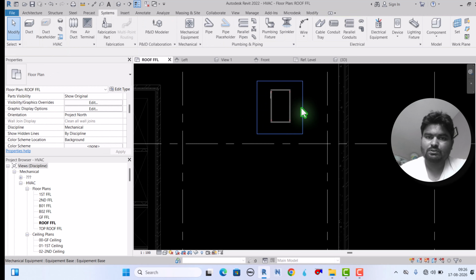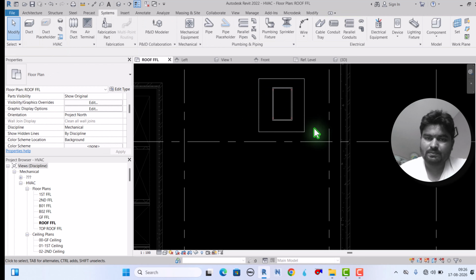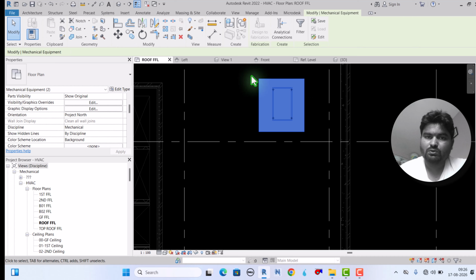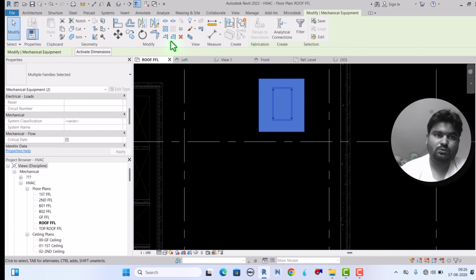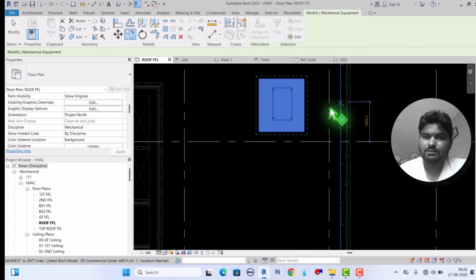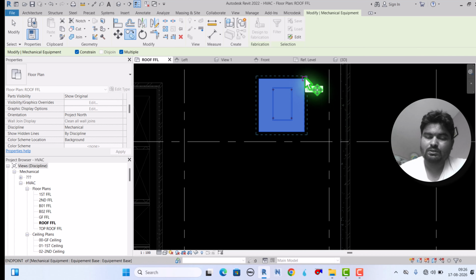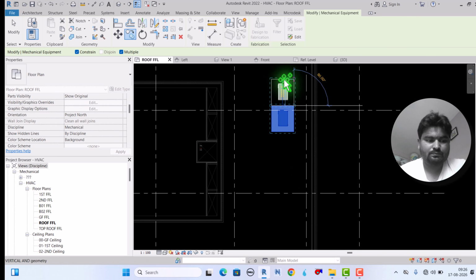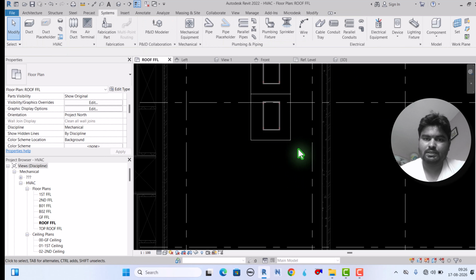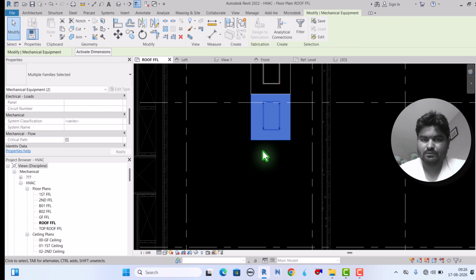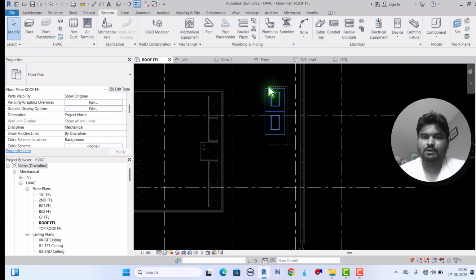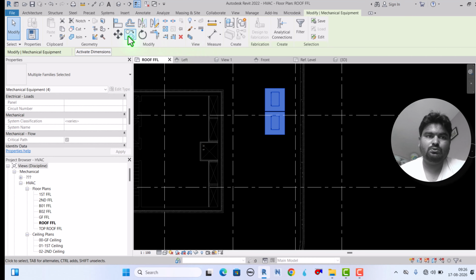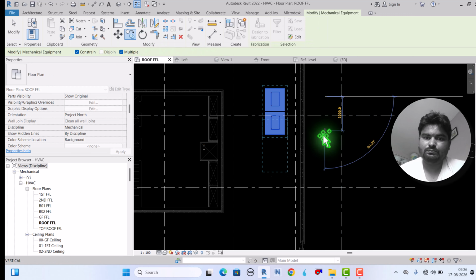Now we can create our pipe and connect in the riser. Okay, so one for retail shop and for the other one we can create similarly, copy and paste, for common areas. Okay, if you want to make some change, okay, fine, and 2 for first floor.